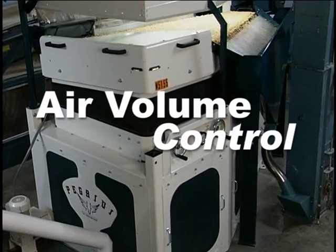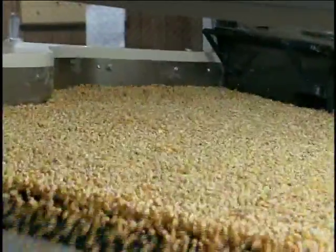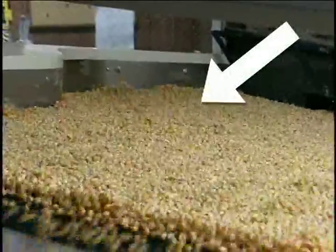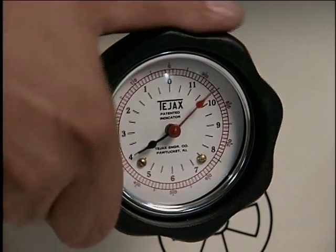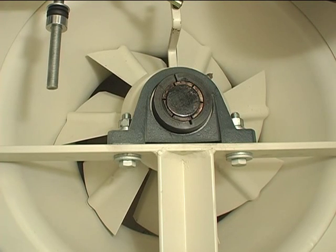Proper air volume is critical for obtaining optimal particle density separation. Remember, air is used as a weighing medium, not a blowing force. Boiling and heaving of the product on the deck is to be avoided. Air volume from the single fan can be accurately adjusted by using the hand wheel located on the operator console. Rotate the hand wheel in the direction indicated to either increase or decrease the volume of air.